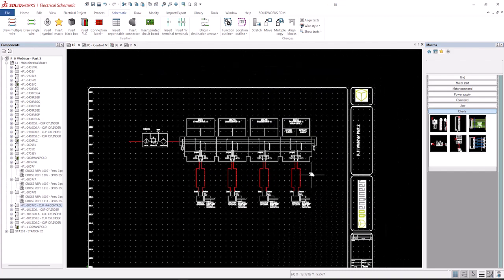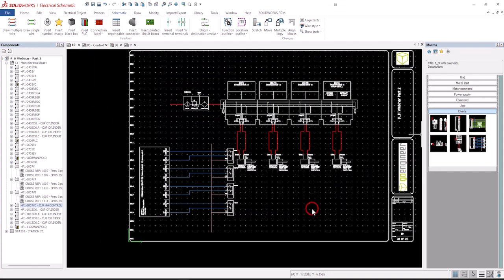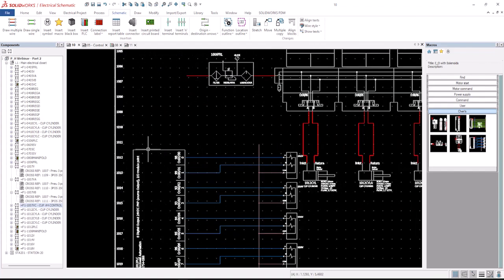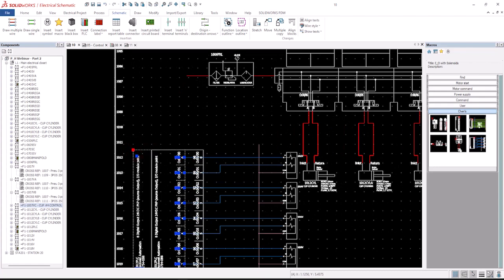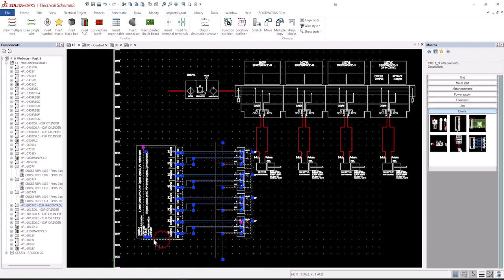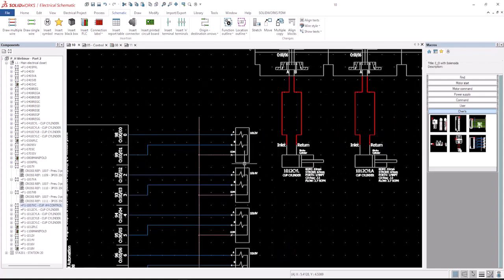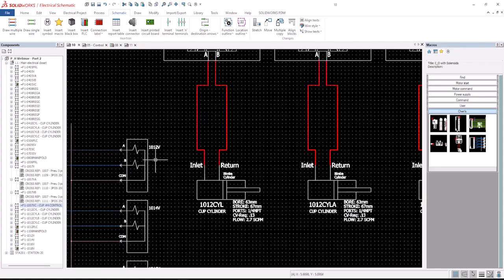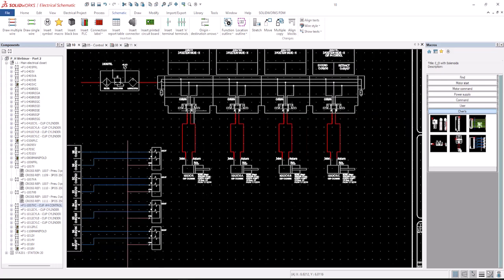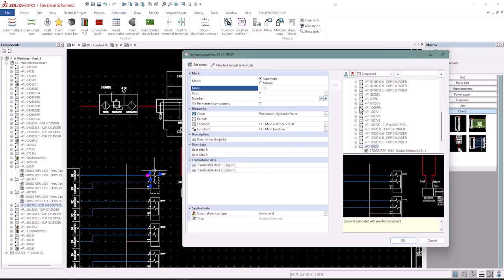I think I'm going to use this page here because I want to put the electrical and the pneumatic schematics all on one page. So I placed it, but now you can see that the symbols are almost overlapping. So I can simply drag to reposition my PLC card, and then I can just drag the entire circuit over to the left. Just remember, this is as if I had designed on the spot, so this is just saving time. Now I'm noticing, of course, I need to make sure that the valve that I am calling out on top is the electrical solenoid.